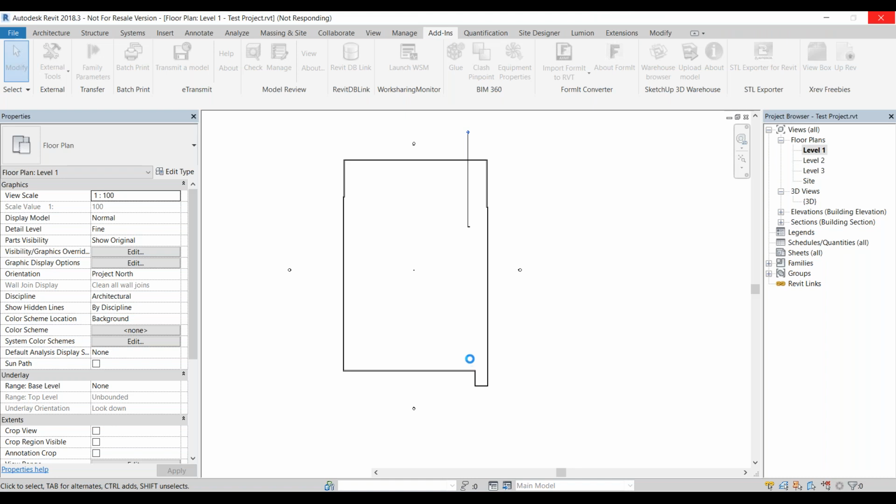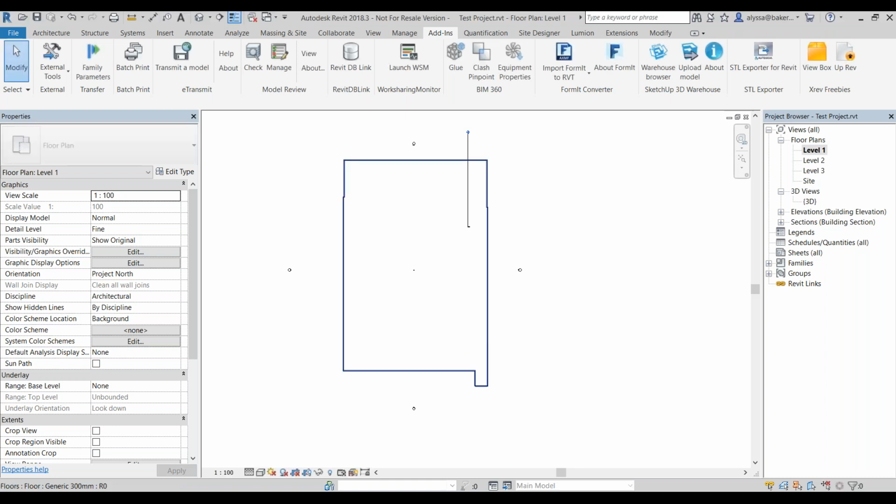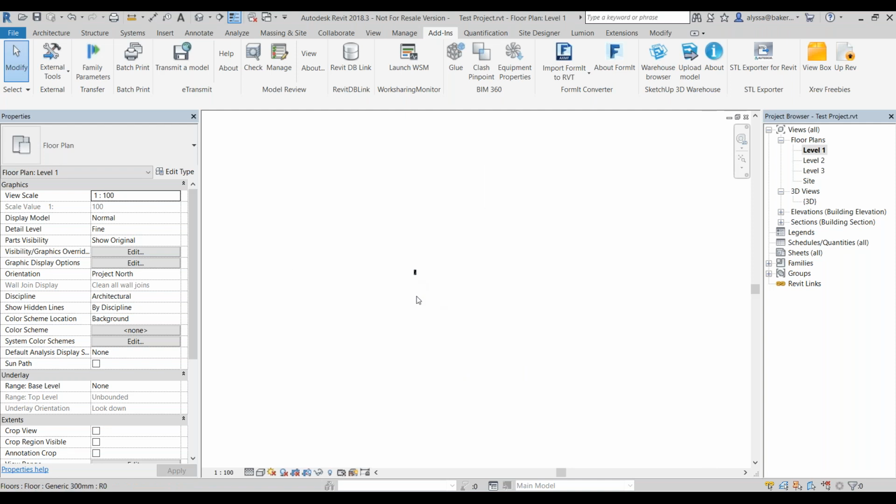Let's wait for it. If you think about parameters and parametrics and so on, you would know that you wouldn't be able to do these things, because we won't be able to add parameters in Format or 3ds Max to bring that into Revit. So our families aren't intelligent, they just come in as what we need them to be. This is why I brought up the topic of suppliers: you may need a furniture piece or something very specific that just looks the part, and if you need it for a render or 3D, this is a great process.